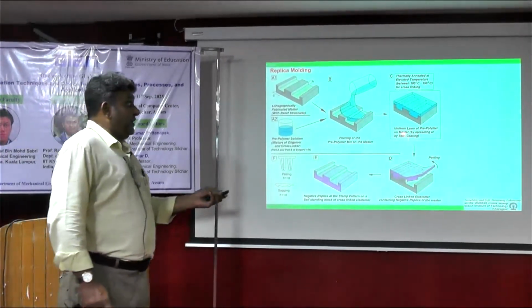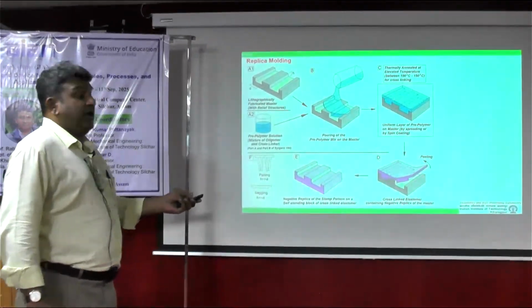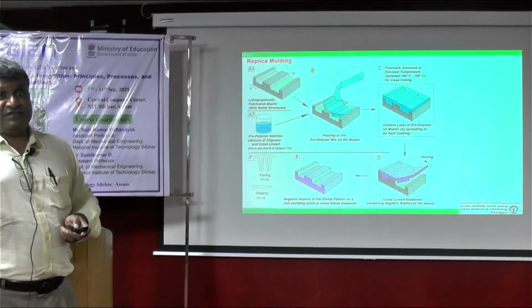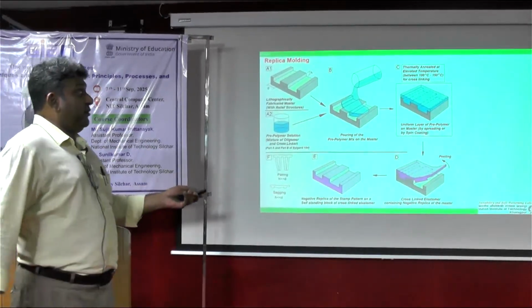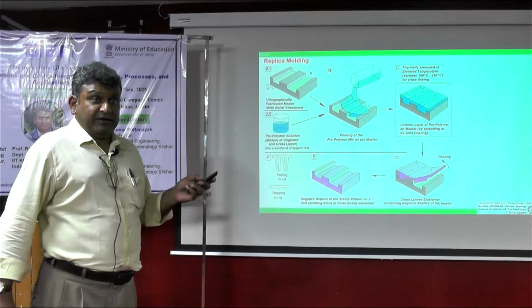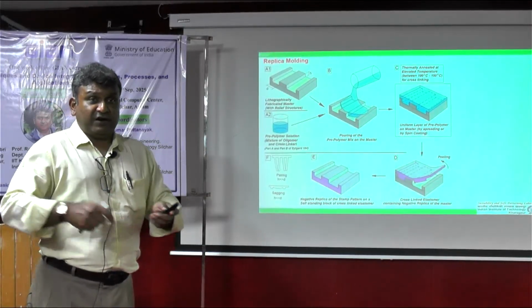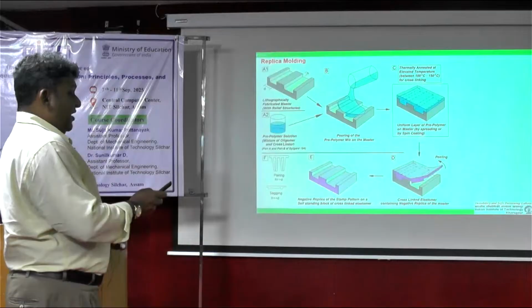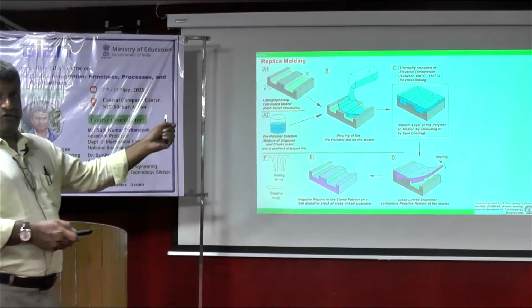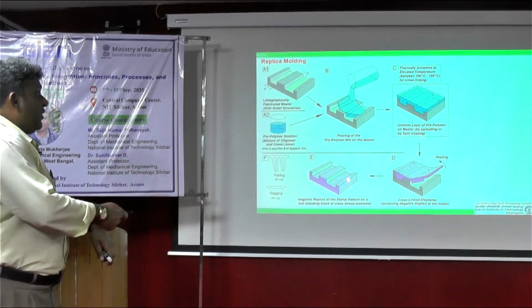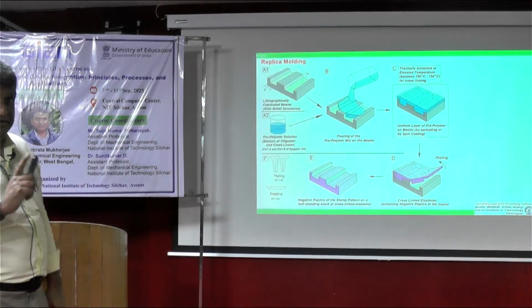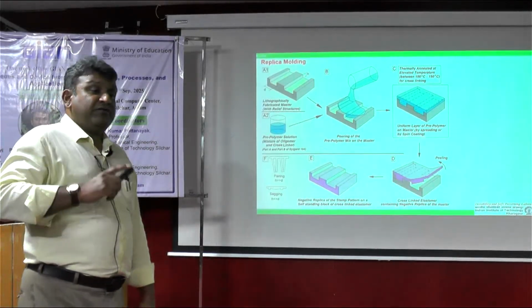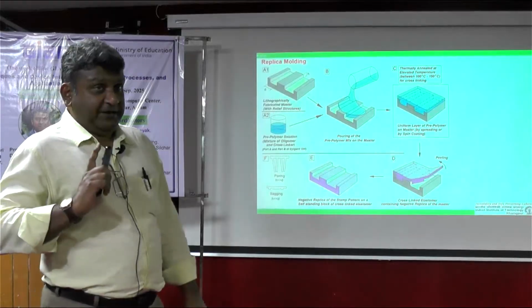Now, as it solidifies, it is solidifying in the presence of a structured surface. So whatever structure was there gets replicated on one of the faces of this block. And it's a flexible solid. So after your annealing is done, you can simply peel it off manually. And in the process, what you have created is a negative replica of the original pattern. But remember one thing, you have created a perfect negative replica, right?